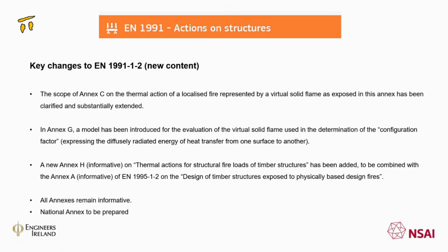There has been further information in Annex C on the thermal action of localized fires. In Annex G, a model has been introduced to evaluate a virtual solid frame, and an Annex H has been put in on thermal actions for structural fire loads of timber structures, which is read with a part of EN 1995.